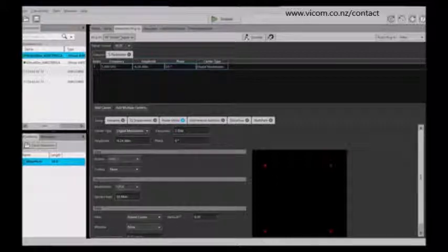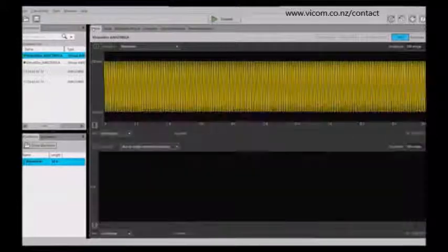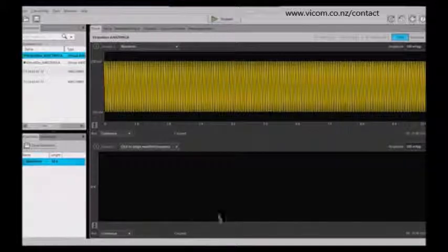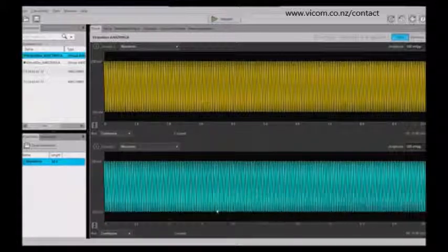So here we're using the RF generic signal plug-in. The other toolbars at the top of the screen are the same as, like I said, on the AWG itself. So the home display would give you the display of the actual waveforms, the criteria. This is a two-channel box, so you can see that I could actually drag the same waveform into both channels. And then if I wanted to play them, I could just play them here.